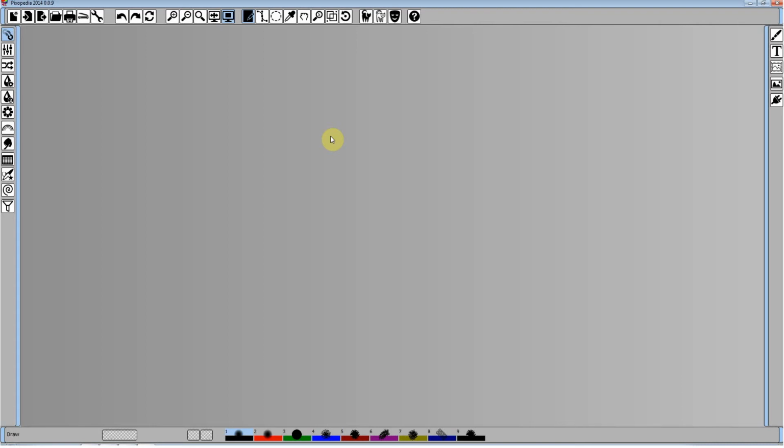Also, initially this button is pressed down, which indicates that standard shapes are on. So we will focus on drawing action with standard shapes. There are 3 most important factors that determine Pixopedia behavior in use. It's action, shape and brush. So in this video we will cover simple drawing with freehand shape, and we will examine some of basic brush parameters.